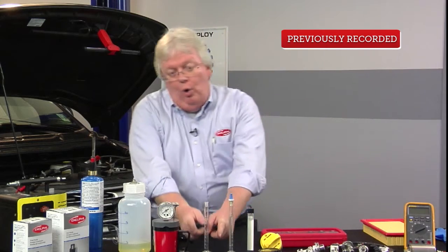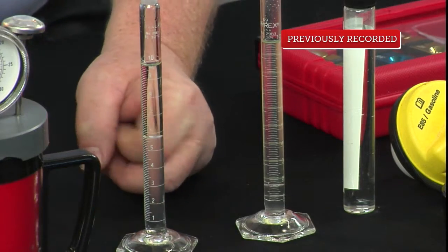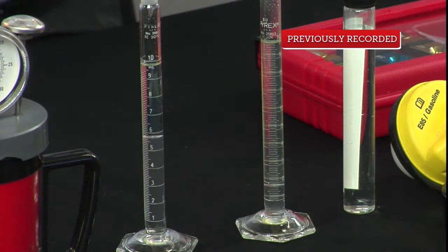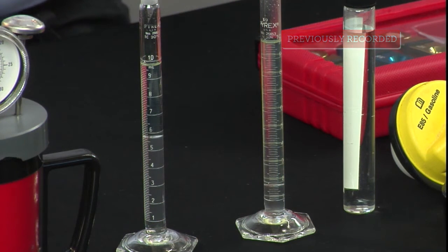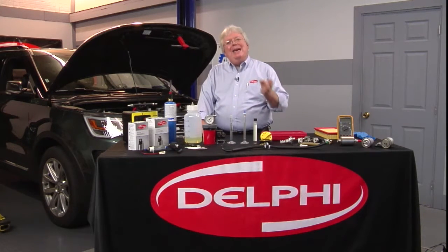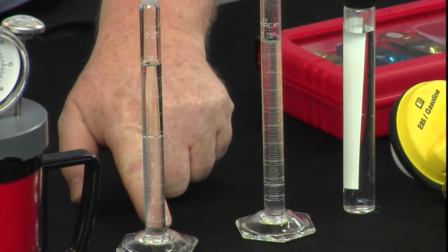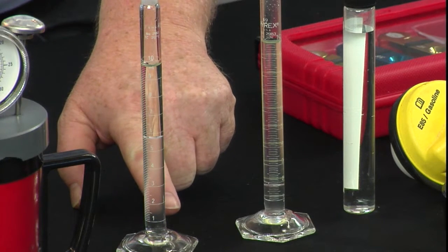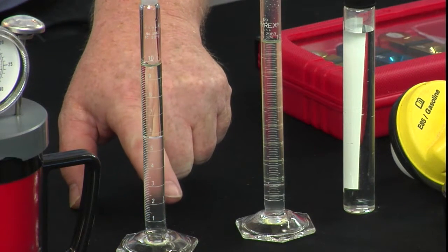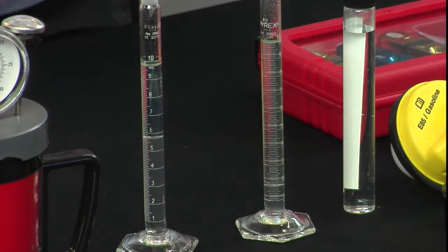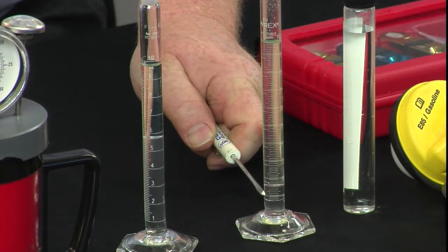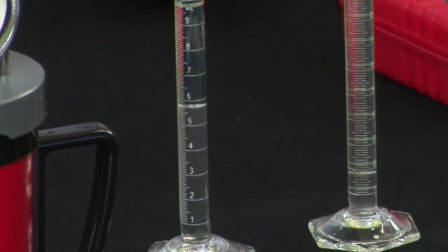On your left here, I have a sample that, again, I put 1 ml of water and 9 mLs of fuel from another test vehicle, but it came in on a wrecker. It wouldn't start. It had drivability issues and it had lean codes. So we did a sample, 1 ml of water, so the separation line should be maybe between 1 and 2. If it was at 2, that would raise it up 1 notch, which would be 10% or E10. But look where the separation line is. Over here it was between 17 and 20.